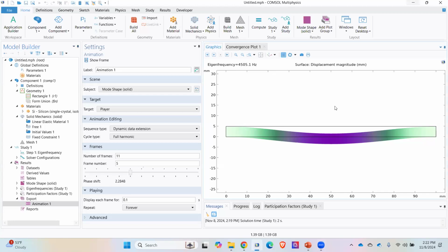You can see many tall buildings or bridges sometimes fail because of resonance. So they always try to keep big bridges and houses far from their resonance frequency, because at resonance frequency your amplitude will be maximum, right? But it is helpful in MEMS devices. Let's say a gyro. A gyroscope will be vibrating at its resonance frequency, so we extract the change in capacitance value when the angular rotation is given.